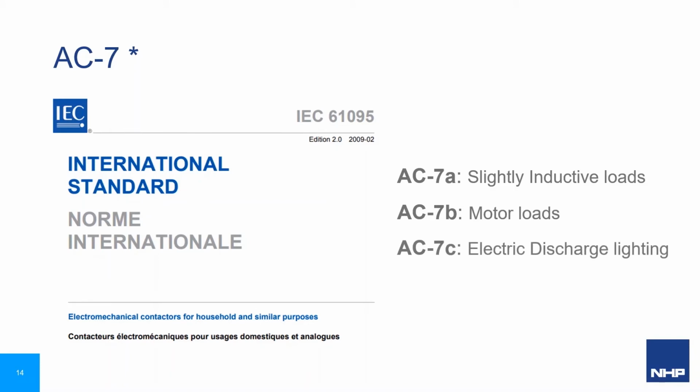AC7B ratings are for motors, similar to AC3. The AC7C ratings are for power factor corrected discharge lamps, with power factor like AC5A, but also similar to AC6B for capacitor switching. It should be noted that these ratings are for household applications and the electrical endurance is less than industrial contactors.